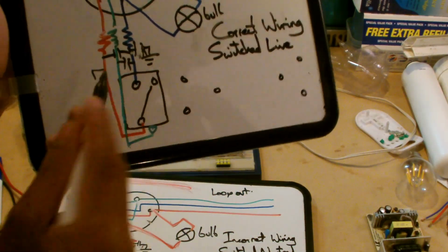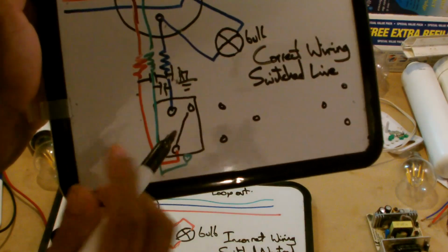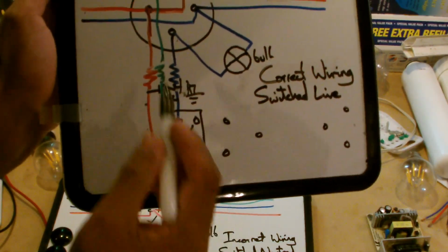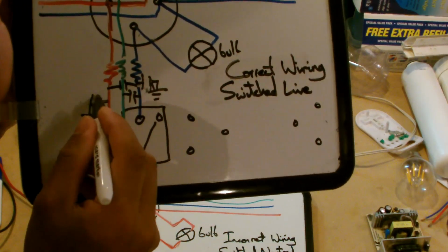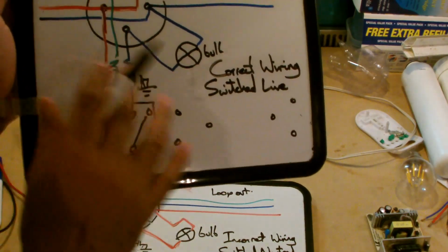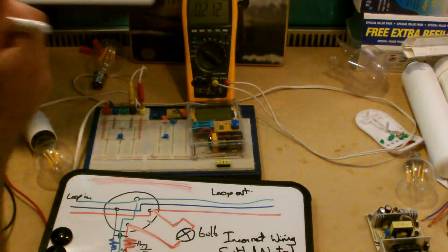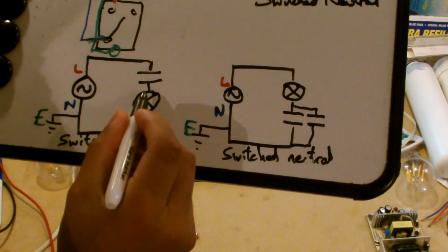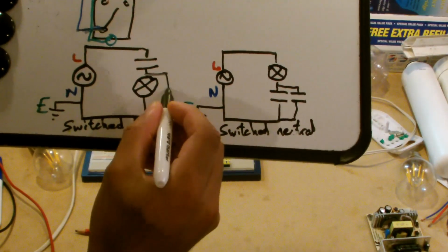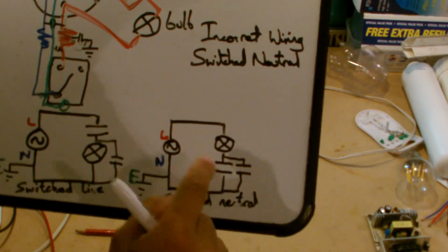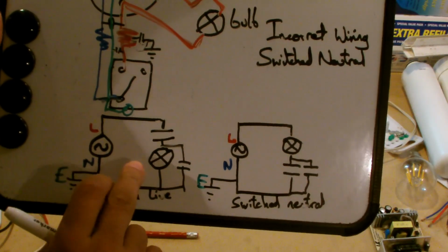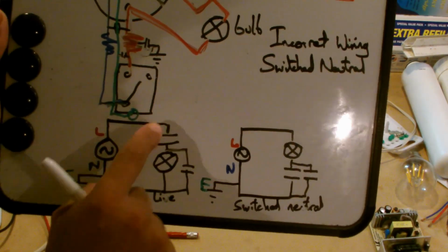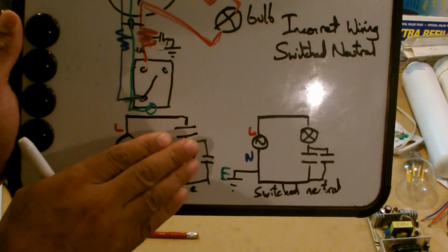which is fixed live. Well, in fact, to be honest with you, that probably is quite irrelevant because it can supply as much power as it likes, so it can supply as many electrons as it needs to. So I think having a capacitance connection to ground is going to be fairly irrelevant for this because it's not going to affect the capacitance. But what's the net effect? If we look at this diagram here, it's going to appear as a cap from here across the bulb. I'm summing up the capacitors and I'm making it worse here, whilst here it's actually acting as a voltage divider, and as I said, when it doesn't hit the target voltage, the clamping voltage, then this is just as though it's just two caps in series.